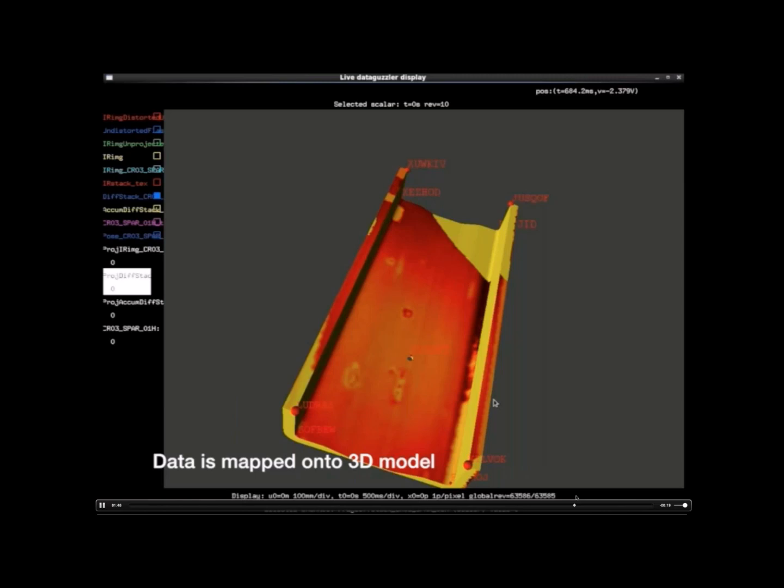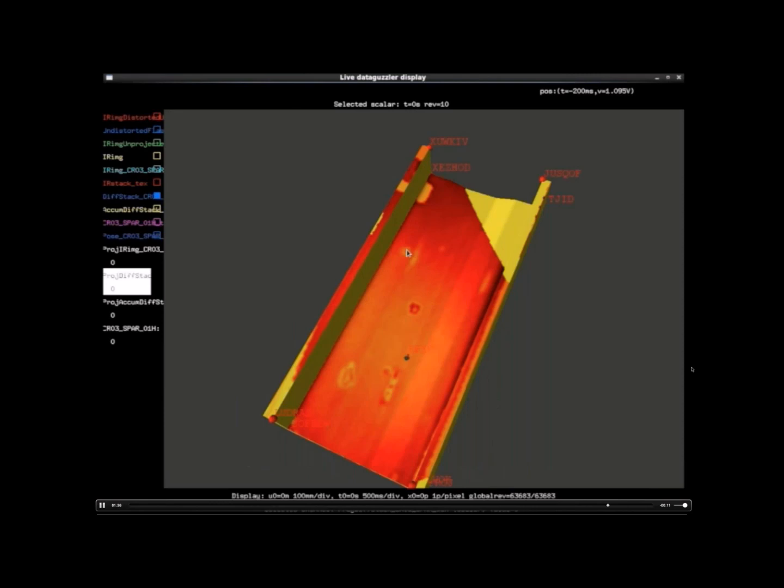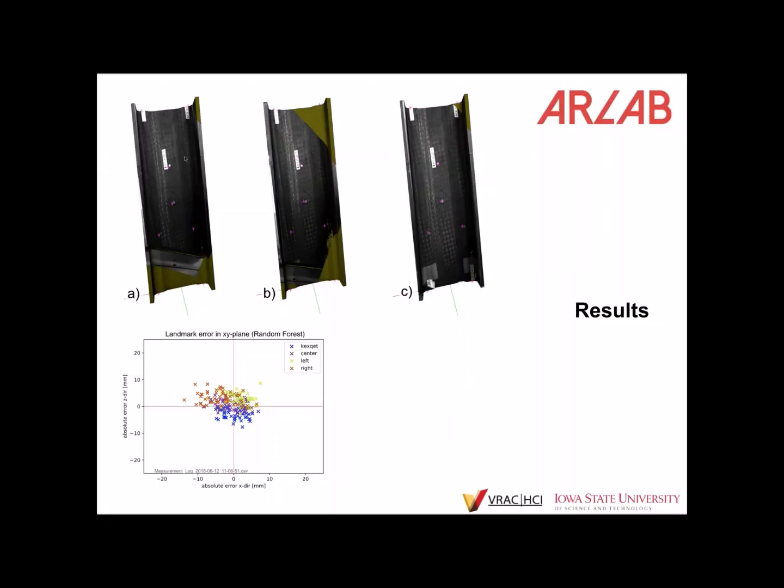So I'd like to show a few results of that, because we were really proud of the accuracy that we can achieve with the camera that we have here. What you see here is this U-star specimen with grayscale data superimposed on it. So we replaced the thermal camera with grayscale data, so it makes it easier to identify landmarks. So we used visible landmarks on the specimen to determine the accuracy here, and those yellow cross marks, or this purple cross mark, show us the location of those landmarks.